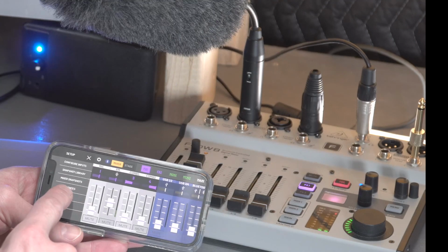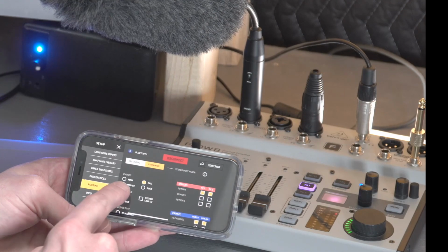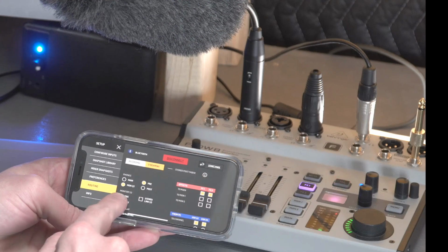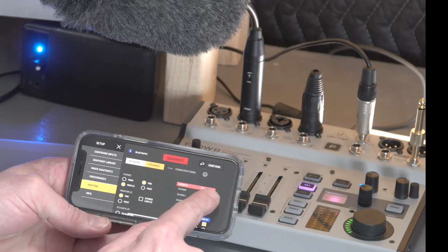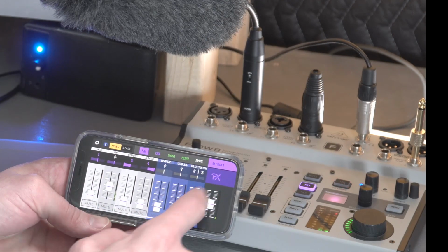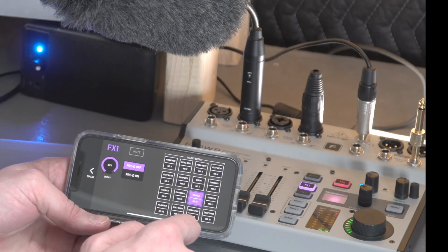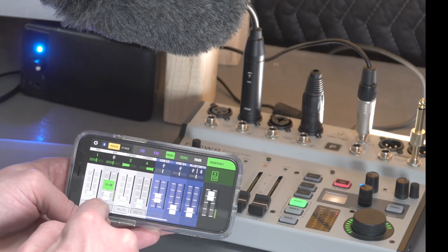So we need to go in here to routing, and then over here on the effects, you can see these speakers are being fed by monitor 1.2 out of the headphone jack. Monitor 1.2 is in pre-fade, and then if I select over here where effects are routed, I can select effects 1 to monitor 1. Hey, hey. Now we can go back to the effects and change the type. Hey, hey, and that is still pre-fade.